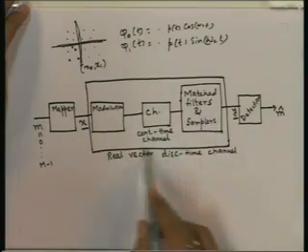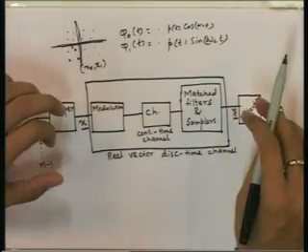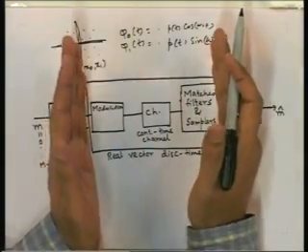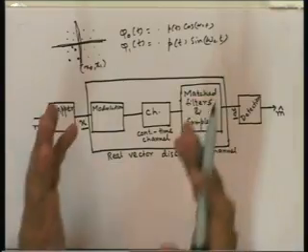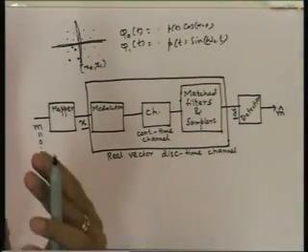another reason for taking this as a channel: we can modularize the design phase. First design the modulation, matched filter, sampler separately, because it is easier to design anything in a modular way. Design first this part in the best way you can, then design the other part in the best way you can, and so on. So, first design the modulation, the matched filter, etc., all the analog parts first, and then once you have designed it, consider the whole block as a real vector channel.